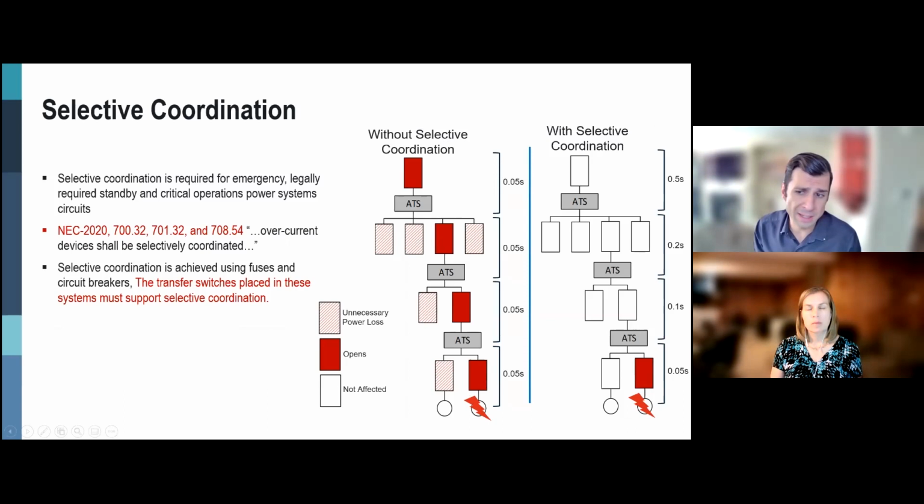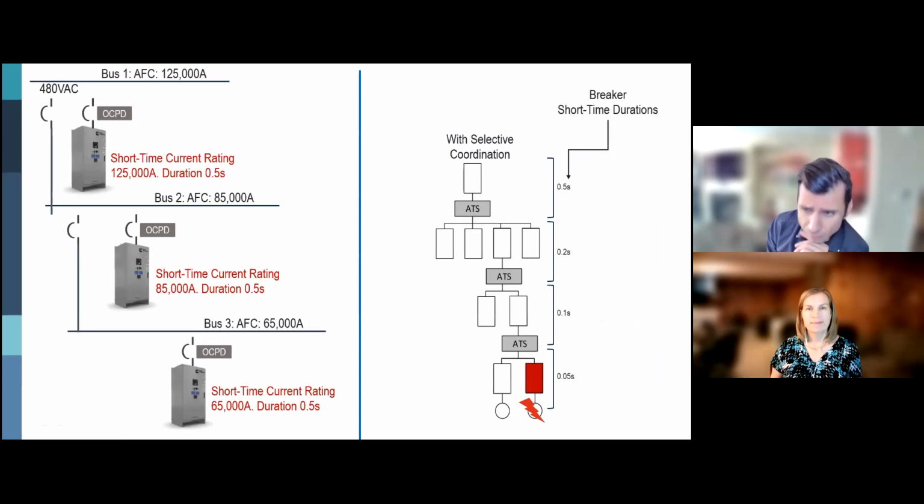What that means is that the transfer switches in between these boards must be braced for that short circuit in that specific branch for that duration. So this is the important thing that you want to get out of the slide. Which takes me to this, and then I've only got one more slide left, and then we'll turn it over to questions.